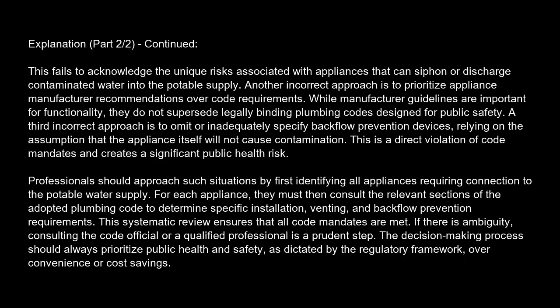A third incorrect approach is to omit or inadequately specify backflow prevention devices, relying on the assumption that the appliance itself will not cause contamination. This is a direct violation of code mandates and creates a significant public health risk.